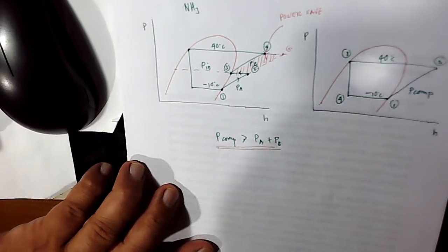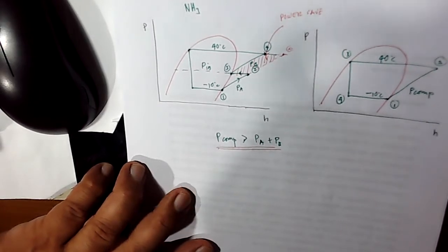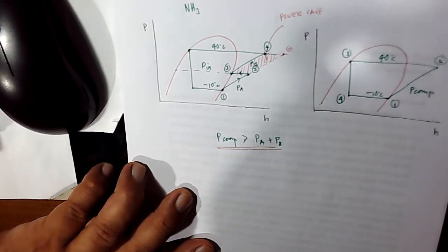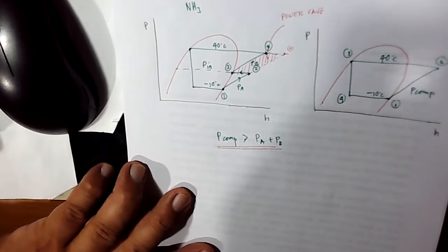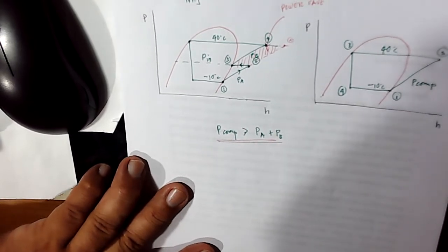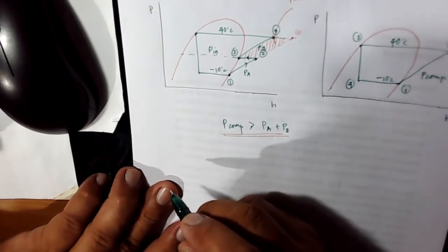So the refrigerant on the high side, or the superheated vapor side, is later on mixed with the refrigerant coming from the saturated or liquid side, of course with the same pressure, because you cannot combine high pressure and low pressure. So the next topic involving intercooler is intercooling with liquid refrigerant.